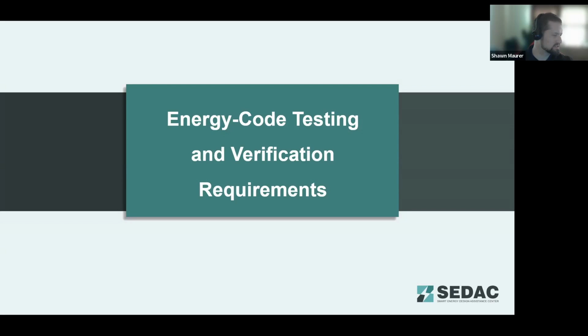We did have a question I see popped up in the chat. For existing commercial buildings, are there companies in Illinois that do pressure testing as a service? I believe that came in while we were doing the building pressure testing. Yes, I think Todd can touch on that a bit more, but pretty much anyone that is certified through the Building Performance Institute or ResNet that can do residential testing could do commercial pressure testing in smaller commercial buildings.